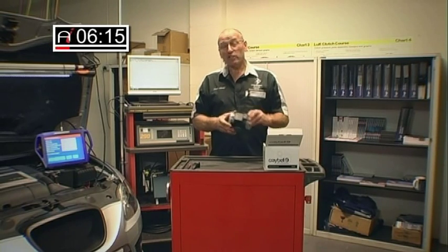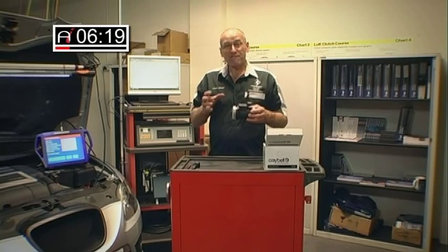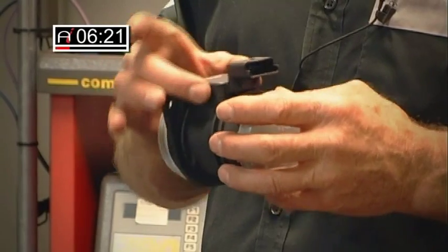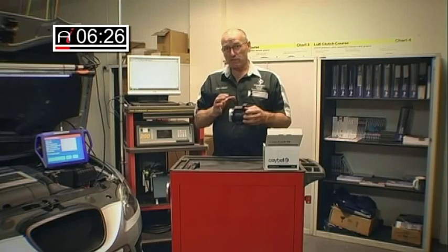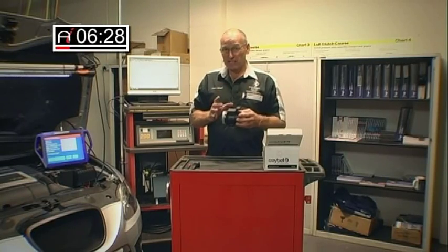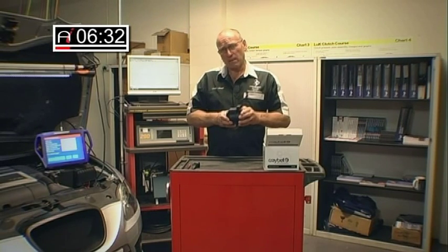So I'd like you to perhaps consider all of those options when you look at a DTC for an air mass meter. The most obvious, of course, and the most common, is that the actual parameters specification of the air mass meter is actually faulty. In other words, the integrity of the system physically is good, where the air mass meter value has changed. In most cases it reduces. I've had the odd case where it's increased. It's quite unusual, but it does happen. And we have to then think about, why does that happen?